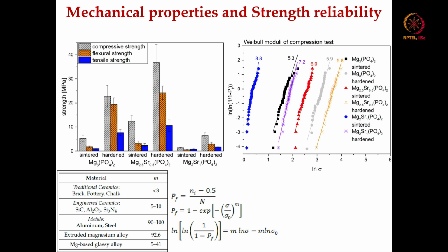Whenever I describe the tensile strength of any ceramic material, you must remember that it was measured by the diametral compression configuration, because the traditional way of making dog bone samples for metallic materials cannot be extended to ceramic materials because of their inherent brittleness. Particularly in binder jet 3D printing, even the porous structures are much more fragile than conventionally sintered 99.9% dense ceramic materials.